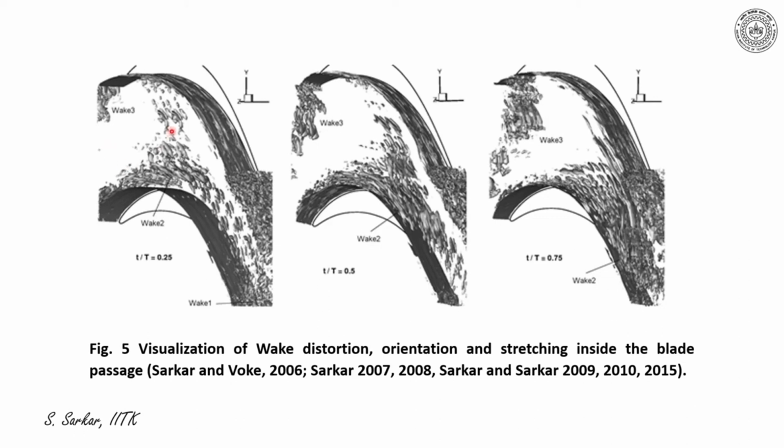Please note that the wake is staged near the pressure surface, while abundant small-scale eddies appear, augmenting turbulence near the suction surface. And these highly turbulent patches will periodically flow over the suction surface, exciting the boundary layer. What appears because of this periodic excitation are multimodal transitions. That is, different modes of transition can coexist, which is very enriched.